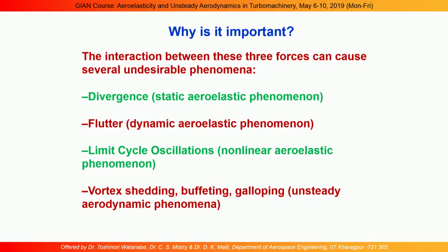Under that condition, if I give a small perturbation, mathematically the deflection will go to infinity, but practically it does not happen, because our analysis is based on linear analysis, and the moment it goes to high deformation, nonlinearity comes into the picture. Obviously it will not have infinite deformation, but when it enters divergence, the deflection will be very high.